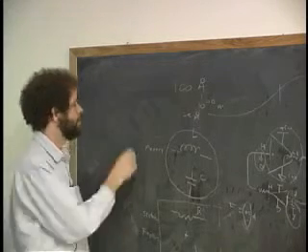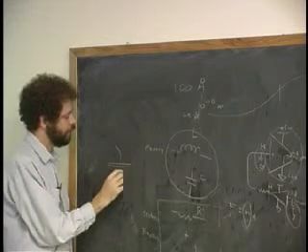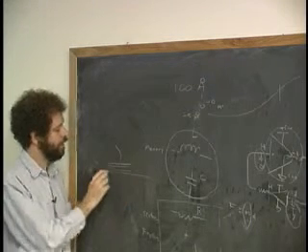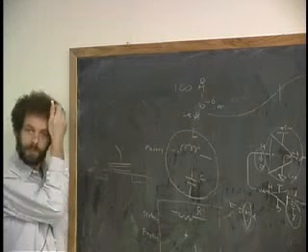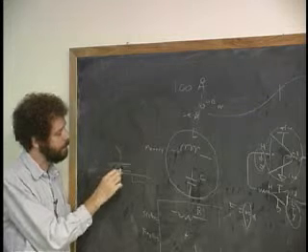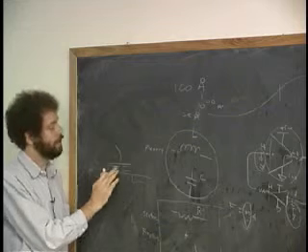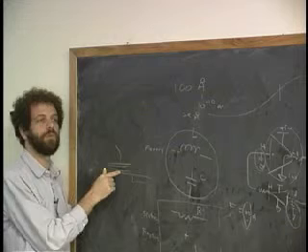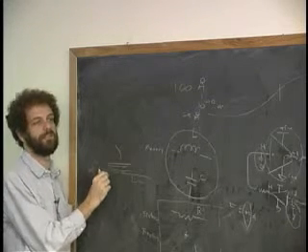There's a phenomenon called punch-through. If this is the gate, and this is this incredibly thin piece of glass underneath it, and here's the rest of the transistor that we've drawn here. If this oxide is very, very thin, first of all, you might make a mistake and the oxide might have a little hole in it here, which would cause this thing to short out to here, which would be bad. The second thing is that the ability of glass to withstand a voltage without breaking down, without getting a spark through here, depends on how thick the glass is.